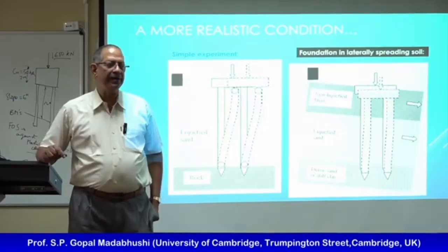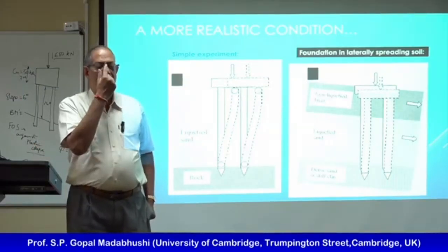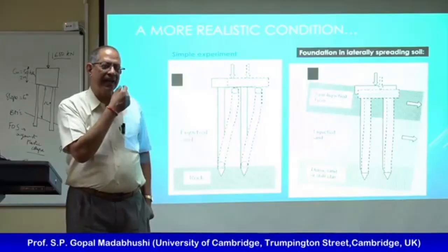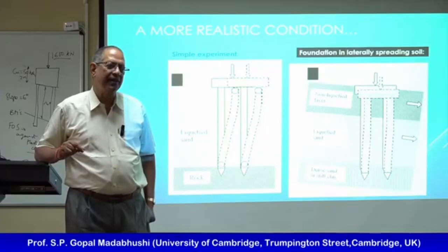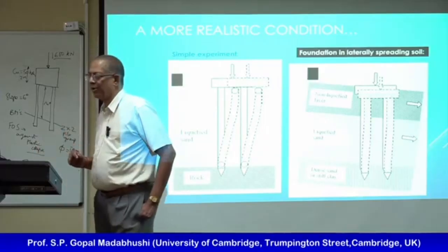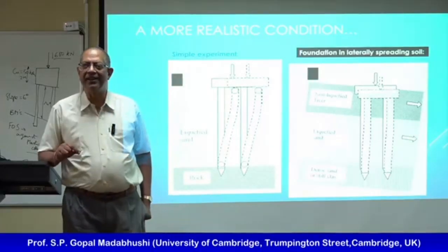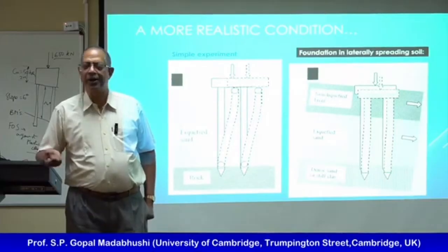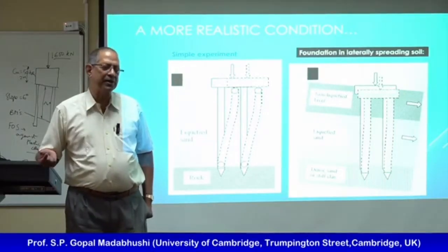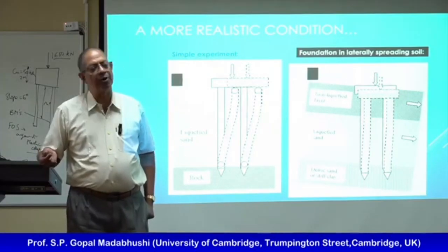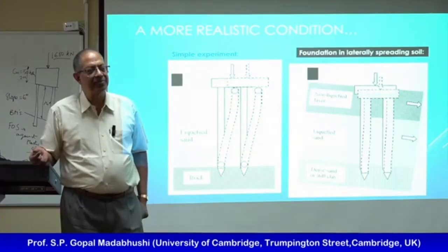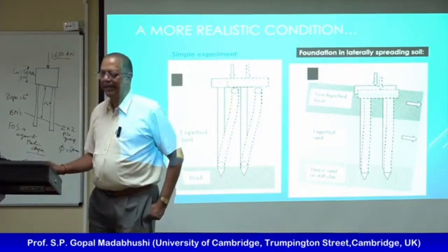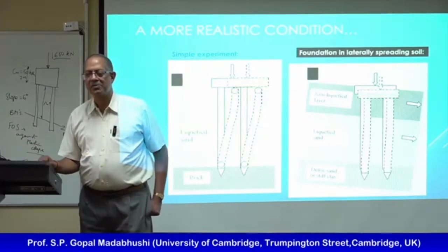But I think I showed you the data for before and after liquefaction in one of the centrifuge tests. That's the paper we published in Bulletin of Earthquake Engineering. The chap is called Seong, Abadi, myself, and Haigh. You can look at that paper. So we clearly see post liquefaction reconsolidation, the lateral capacity of the monopile increases because the soil has densified. All right? Anything else? Very good.